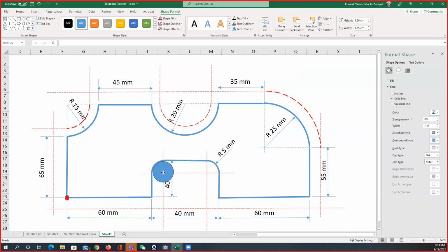Now, can we actually later make the corner to be acute? The answer is yes, but we're not going to use the milling operation. Later, we can do something like the broaching operation, where the cutting tool will just keep going forward and backward and remove the rounded edge and make it, instead of the fillet, a straight one with a 90 degree angle. Okay, so this is something we don't want to worry about at the moment.